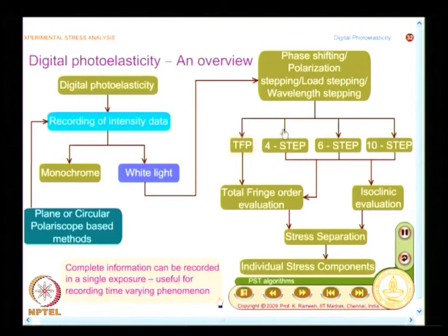And if you look at the literature, I said isochromatic evaluation is very, very important. So, the initial focus was on methodologies to get isochromatics. Only when people realized we also need isoclinics, they found out that they need more optical arrangements to get this precisely.